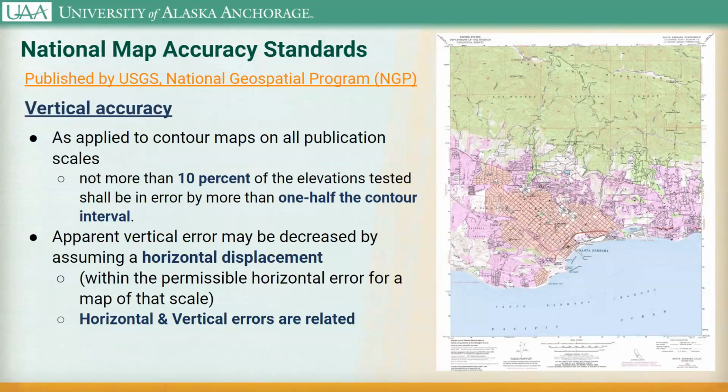Similarly, there's a standard for vertical accuracy. When we're talking in a 2D environment, vertical accuracy is a little bit harder to define than it might be, for example, for sonar data collection. I'm going to define it in much the same way that I do horizontal accuracy, because I'm looking at things in 3 dimensions. So I'll expect an accuracy of a depth in the water based on a known water depth. So I'm going to compare it to something that I've measured directly using an independent system.